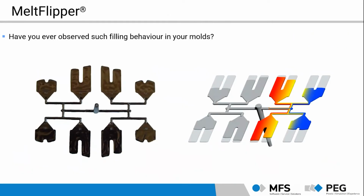Have a look at these two pictures. You see a short shot of an 8-cavity mold with a cold runner system. We can see that all runner sections for all cavities have an equal length and equal diameter. Venting is not a problem here, so we expect a balanced filling. But the reality shows that this is not the case. The inner cavities are already more filled with material than the outer cavities, or in other words, the inner cavities are filled faster. So what is the reason for this effect?